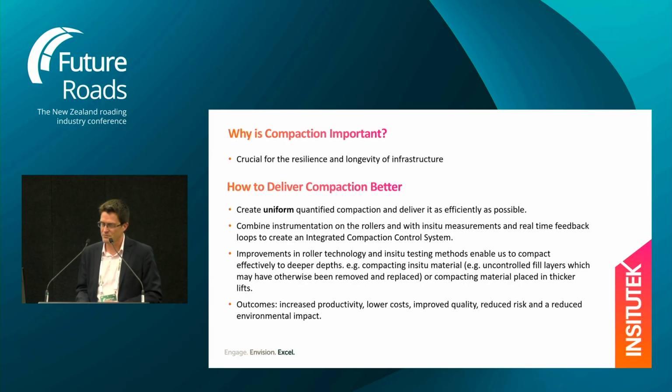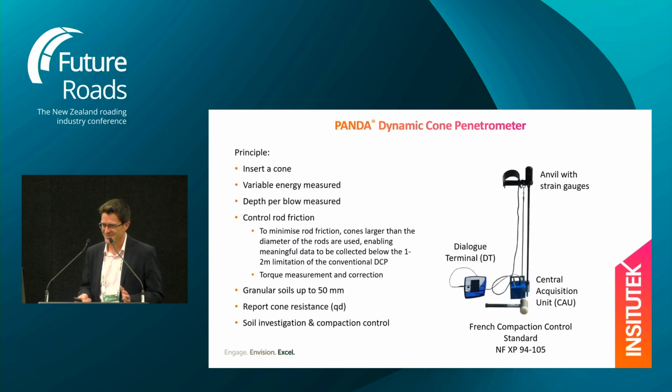What we're interested in really is stiffness. When we design pavements, we typically design using stiffness or a modulus. And so what we actually want to be able to assess is modulus in situ.